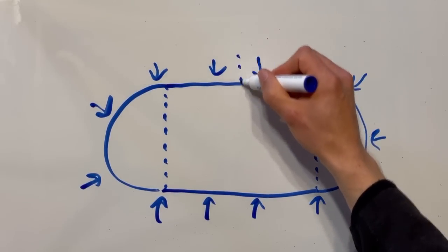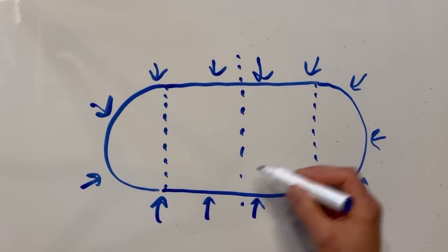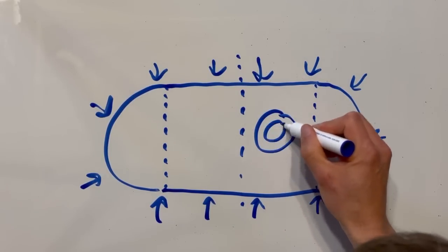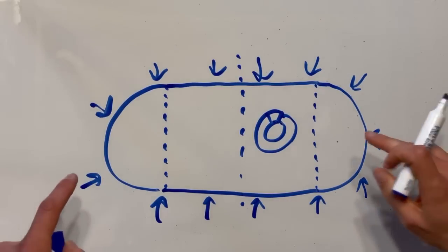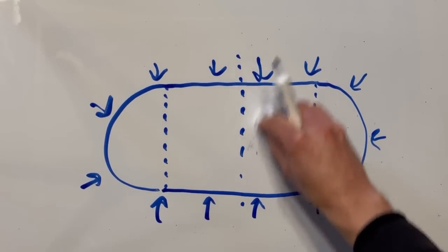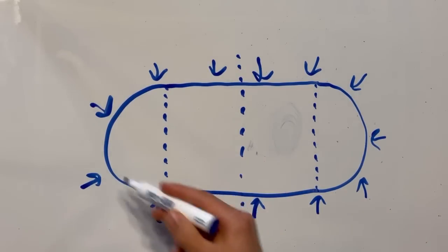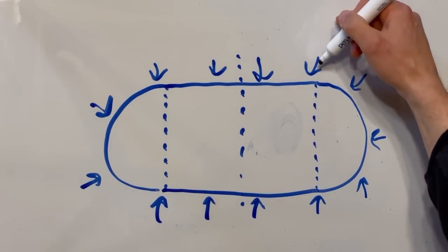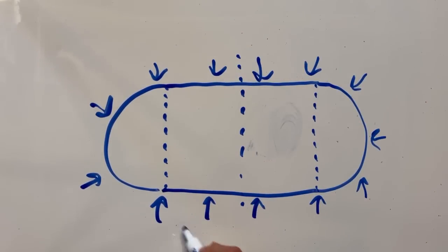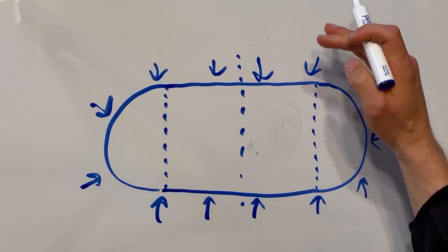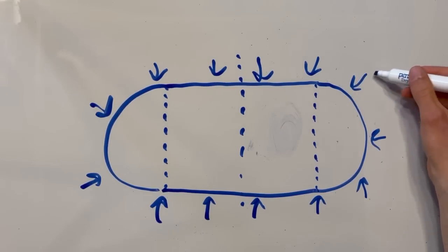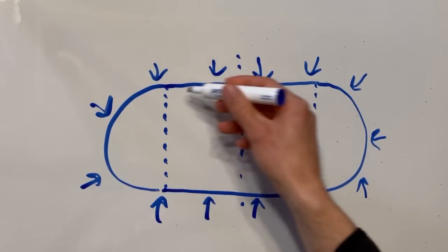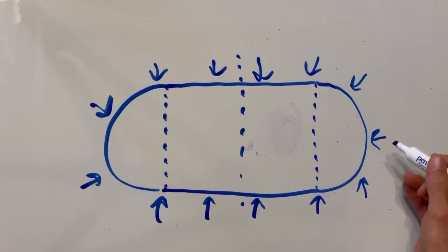If I go ahead and slice this down the middle, that composite tube is still going to have that cylindrical cross section with the keystones. But in the larger picture, what happens with all these forces? So the forces coming in, say, from the top in this example and coming up from the bottom cancel out in the compression of that circular cross section that we did before. But now the ends here are pushing in on a long straight section.